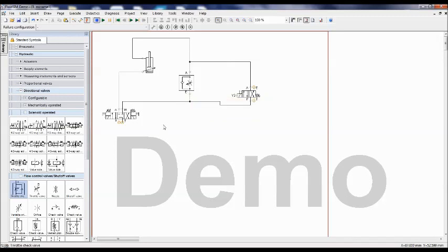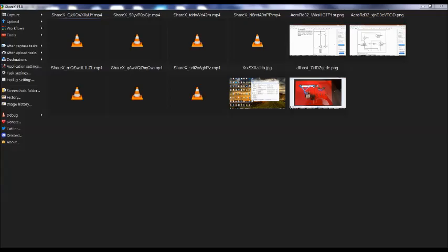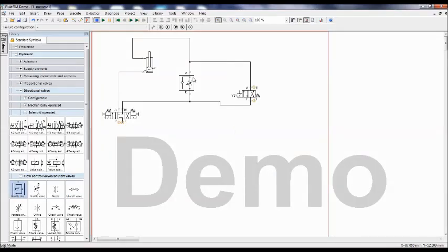So if solenoid Y3 is off, you can assume that it is slow speed, because oil is forced to flow through the throttle valve. Throttle valve means you can adjust it for low speed or high speed, but we are always adjusting the throttle valve position in low opening position, so always low speed.